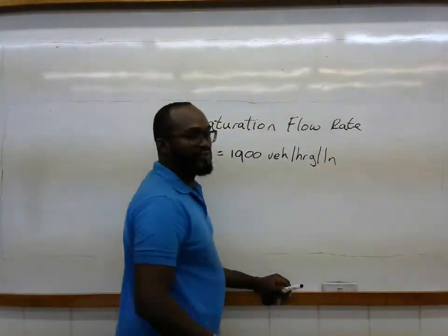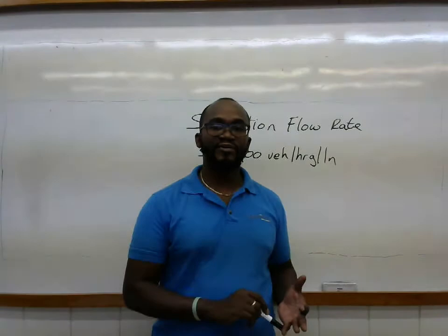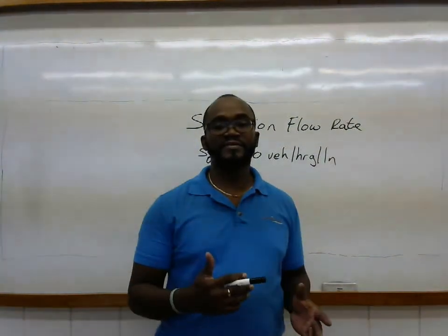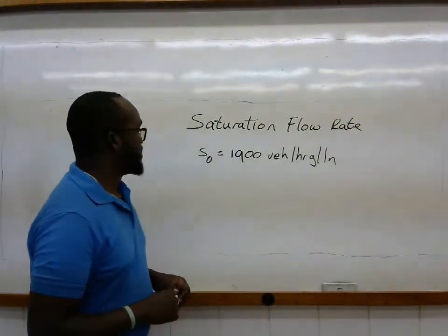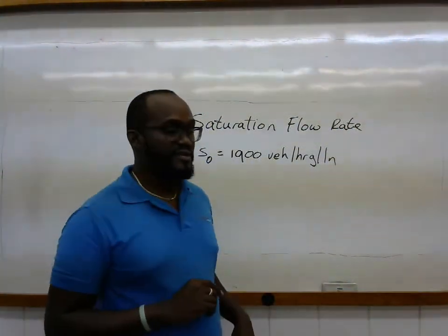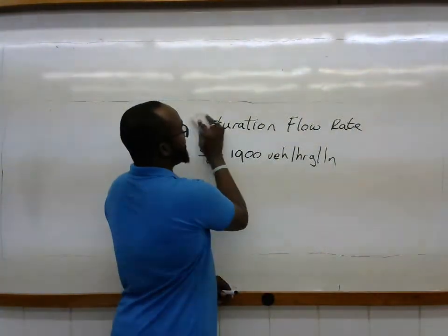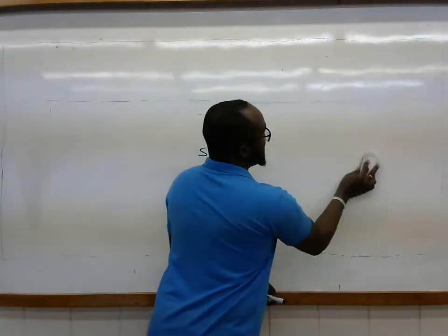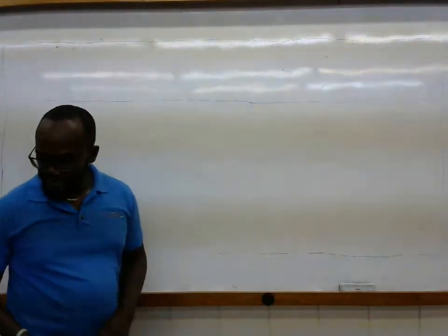So in your case, you would have had the practice of measuring the field saturation flow both manually, and in some cases, some groups actually did it using traffic counters. So that's one way, but there's also the theoretical saturation flow, which is computed from, again, the Highway Capacity Manual, which gives a specific formula for estimating that, and it's as follows.